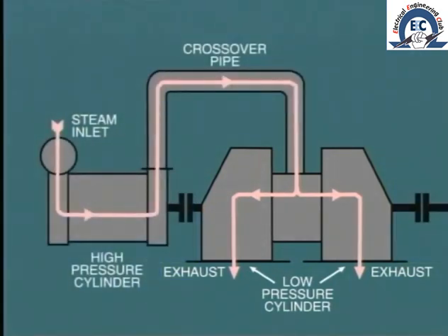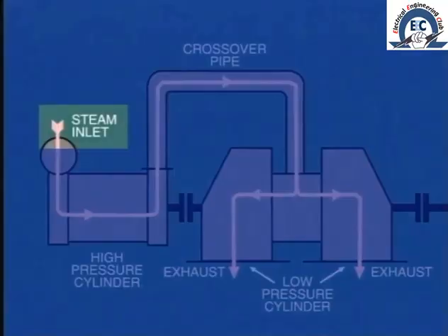As the steam path of the high-pressure and low-pressure cylinders is in series, all of the control is carried out at the steam inlet admission valves at the high-pressure end.